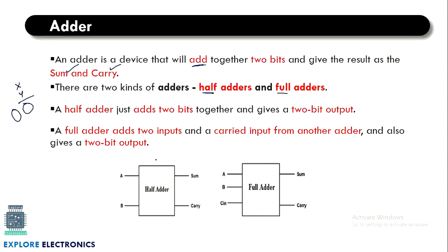What is half adder? Here you can observe this is the block diagram of the half adder. In this block, we will be having a circuitry which is functioning as half adder. We are representing it with a bounded box here. This half adder is adding 2 bits as I said, and the output will be 2 bits. Let me take the input as A and B. A can attain a value 0 or 1, B can take value 0 or 1. So if we add these values, we will be getting sum and carry. To generate sum and carry, we will be having two outputs.